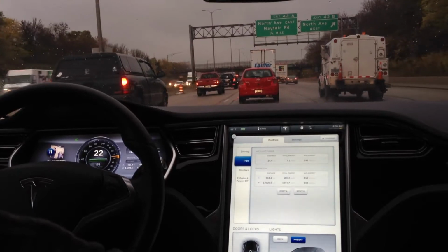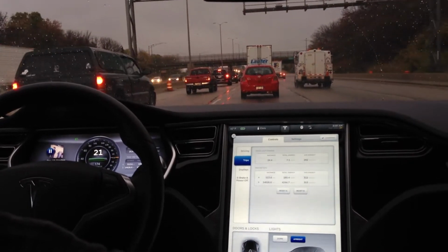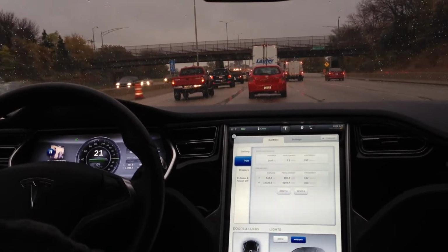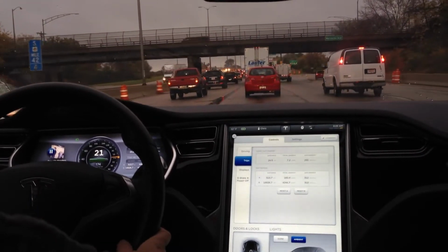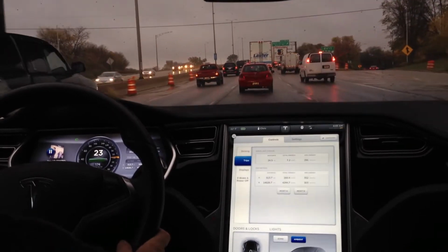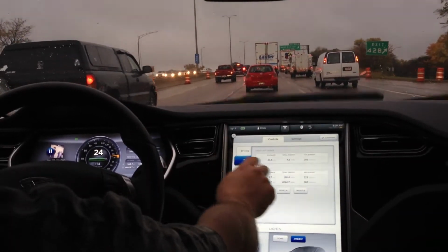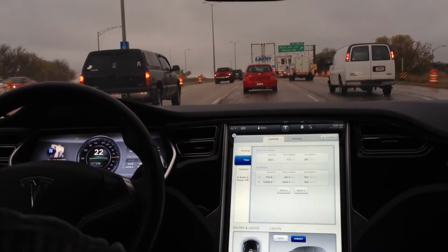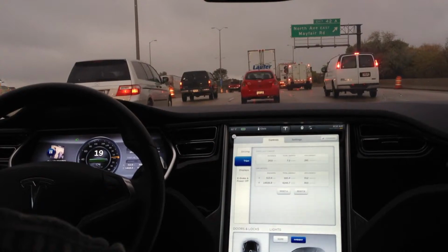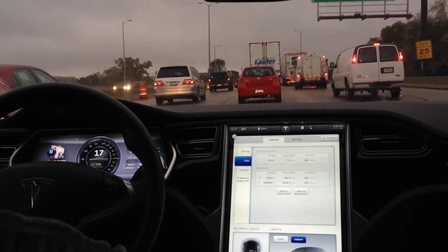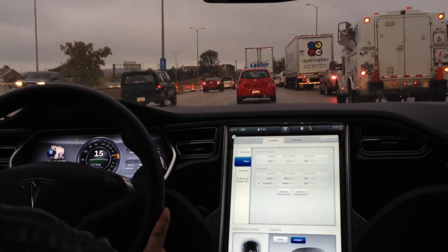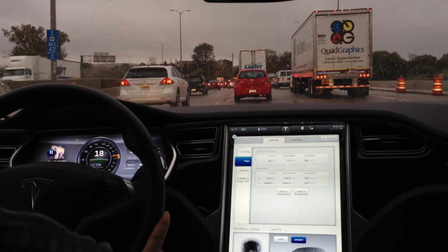Now, to calculate how much you're using, say the vehicle is cruising along and consuming 10 kilowatts. If you maintain that for 1 hour, you have just consumed 10 kilowatt hours. So in other words, kilowatt hours, that's what you're getting billed at by your utility. Now my time of use electrical rate that I charge up at is 5 cents a kilowatt hour. So that would be 50 cents to drive for 1 hour at exactly 10 kilowatts of power consumption.